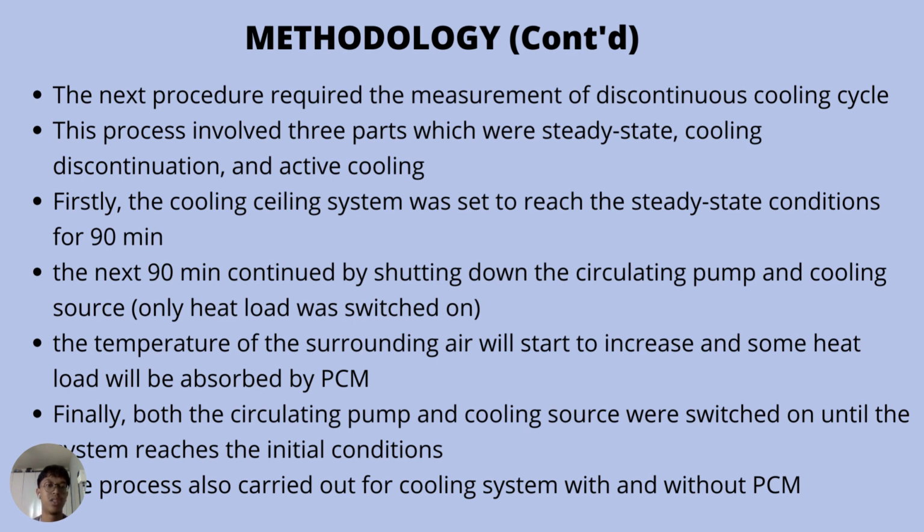Firstly, the cooling system was set to reach the steady state conditions for 90 minutes, and the next 90 minutes continued by shutting down the circulating pump and also the cooling source, where only the heat load was switched on in the test chamber. During the discontinuation process, the temperature of the surrounding air will start to increase, and some heat load will be absorbed by the PCM, the phase change material, in the cooling ceiling box.